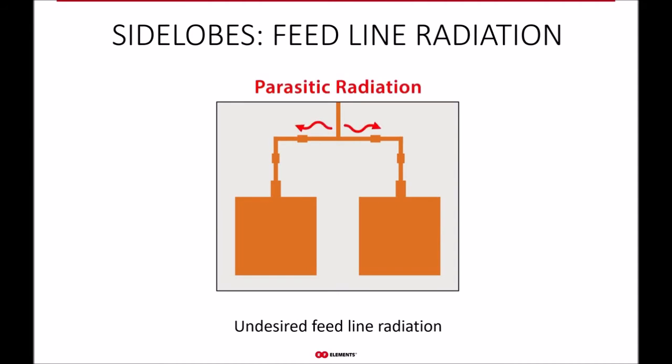So the feeding line is composed of metal strips of varying width and shapes. And these have their own resonances that help, on one hand, extend the bandwidth of the whole antenna, which is a good thing, but also makes them radiate part of the energy before it reaches the patches, which is a negative feature for a WISP sector antenna.